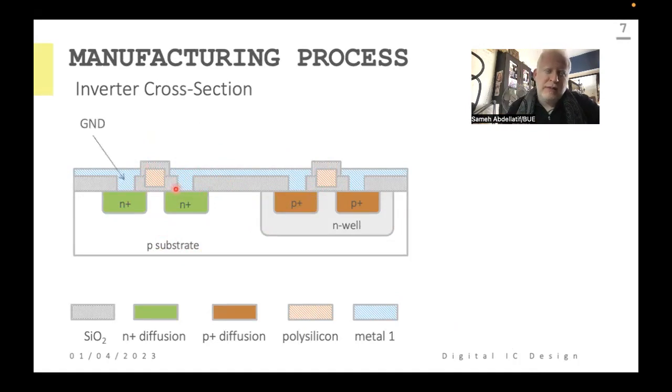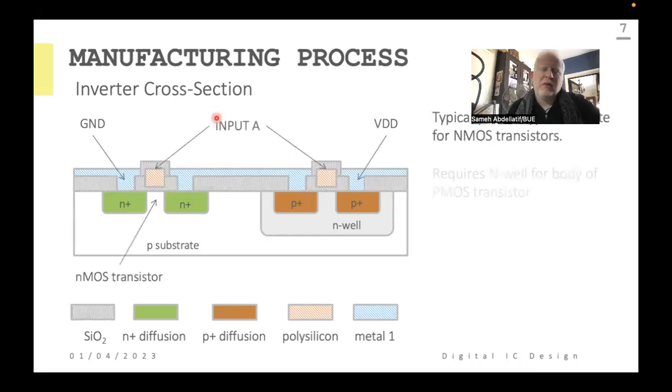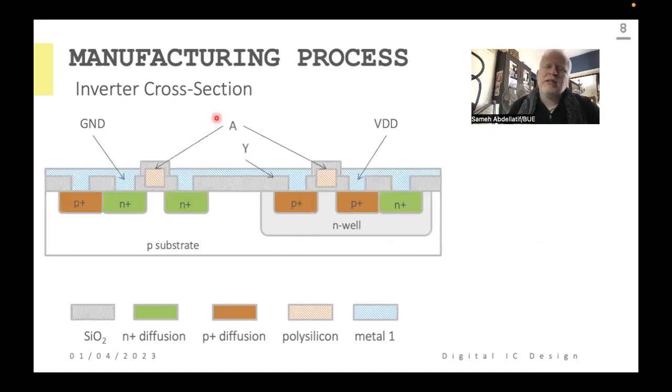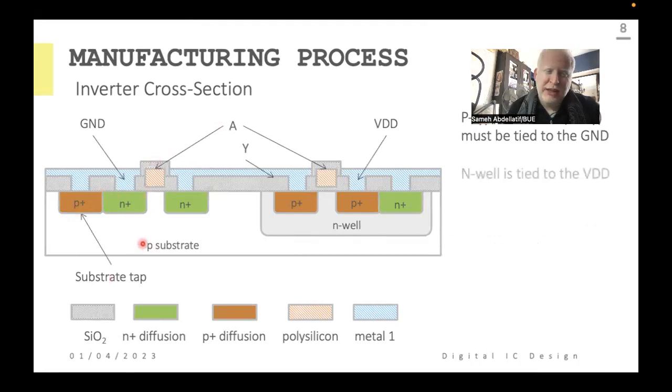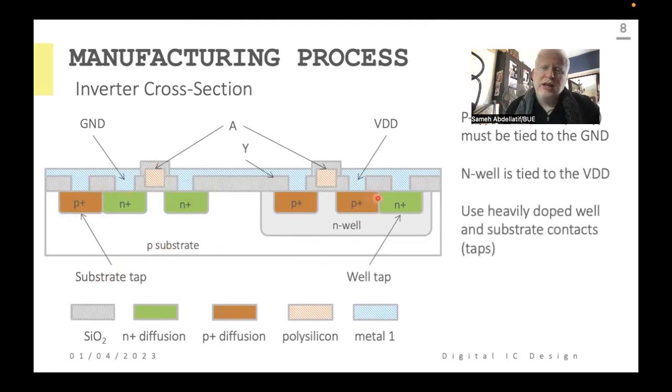And I'm not sure if all of you have studied digital courses or not, but one of the added points here is what we call the substrate and the well taps. These added two regions, this substrate tap and this well tap. These substrate tap and well tap are very famous in the digital technology, and they are implemented for the purpose of eliminating what we can call latch-up. The latch-up is the process of having a direct connection between the VDD and the ground in a transistor.